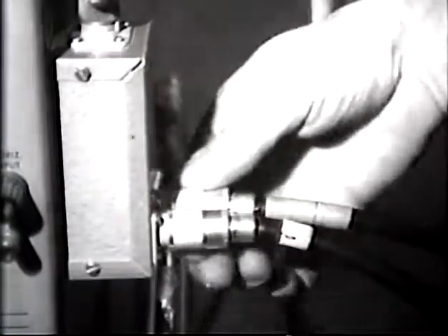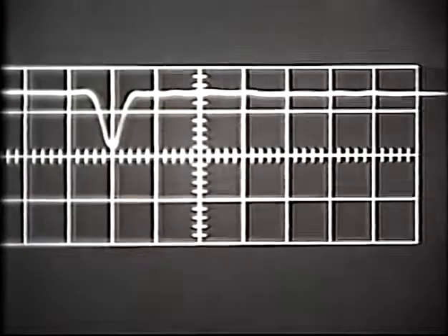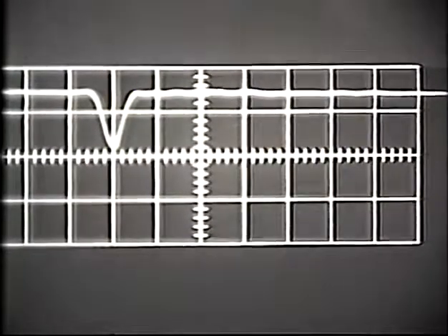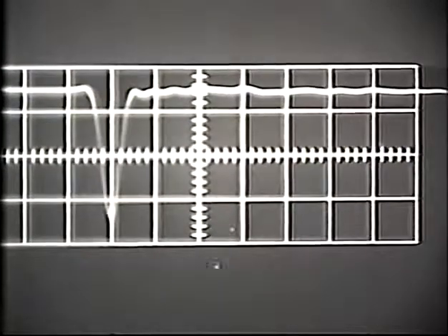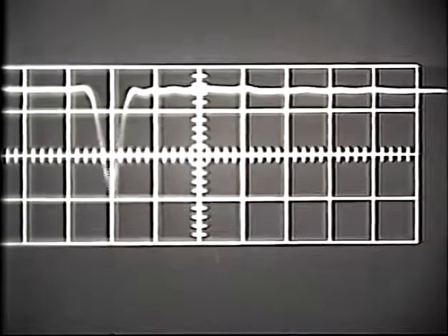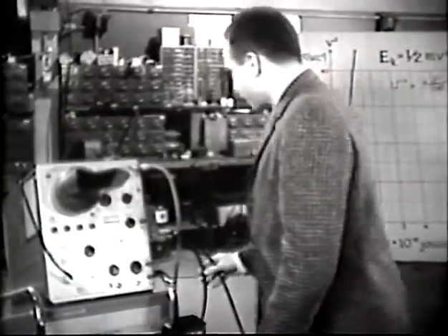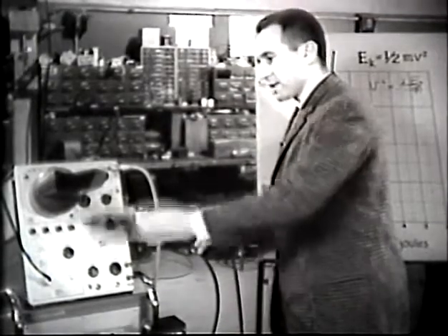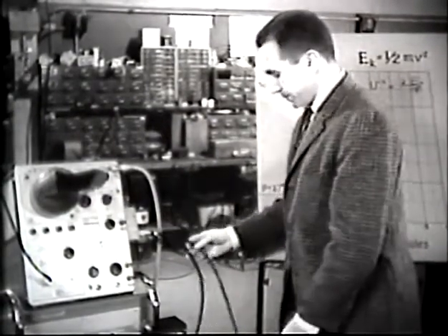I'll disconnect this first cable. You see that the signal coming in through the second cable alone is in the same place as that from the first cable. I'll connect them both again. Once more, we have the larger signal. So signals starting down these cables simultaneously appear simultaneously on the scope. The cables are indeed matched.